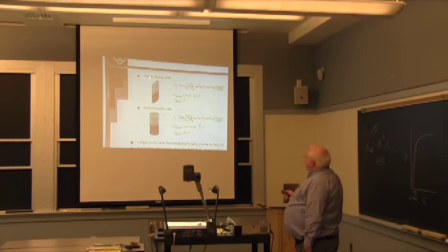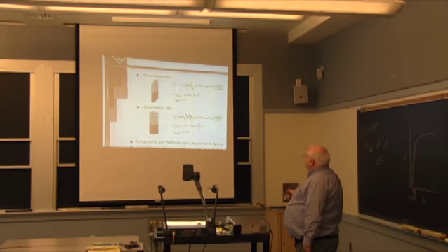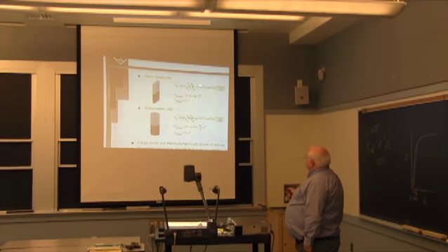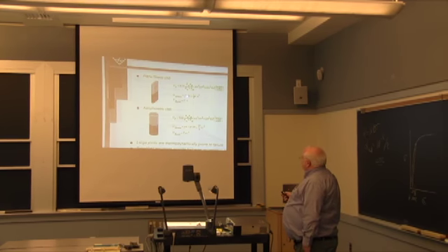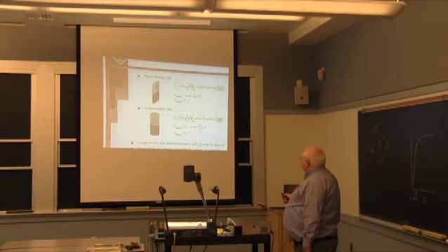Okay, so if I look at plane stress, just a flat slab, and look at the strain energy, you can write down a formula, which is there's the difference in modulus of the two materials. So this is the elastic effect. Delta alpha squared, delta T squared, width squared, error function. It's being relieved as you go further away from the interface. But in any case, the strain energy, you can think of it as a spring, and you've got 1/2 kx squared. That's the strain energy.